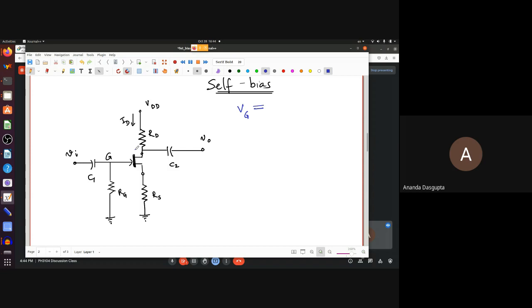Ideally, if you just had the channel, nothing else, didn't have the p-type doped into it, it would just behave like a conductor. The reason why the channel becomes narrow, etc., is because you have a p-type semiconductor built in, which produces a depletion region and all that. But here we have a gate to channel. Gate is p-type, channel is n-type, and is reverse biased. How much current would flow?